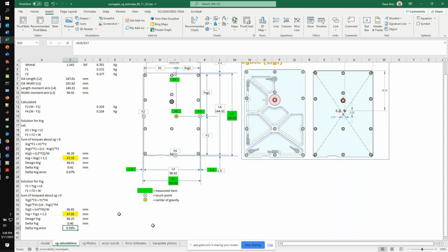You know, could it be that the way they were manufactured impacted the results? And so there needs to be an additional specification for how to make sure that doesn't happen, I guess, is where my brain goes. So I'm not sure how many of the other hard drive manufacturers or other chassis designers have access to a rotational shaker. Data Physics makes a really nice rotational shaker, and that would be the way to calibrate the rotational accelerations as opposed to the linear.